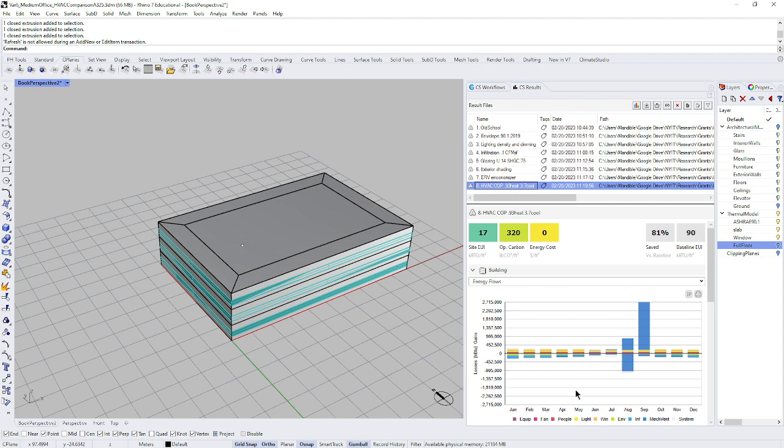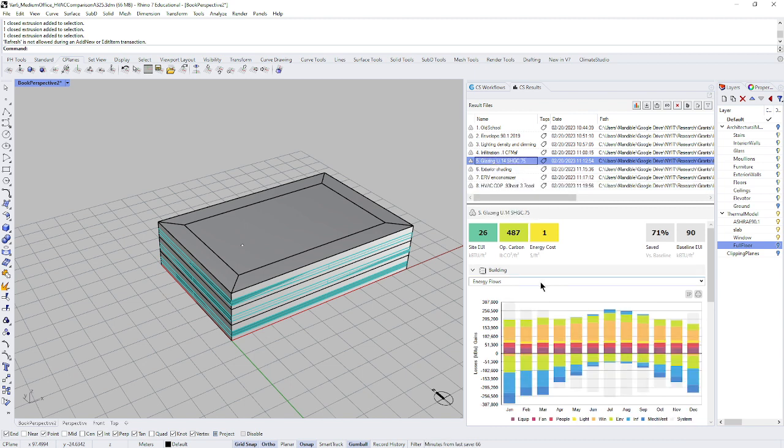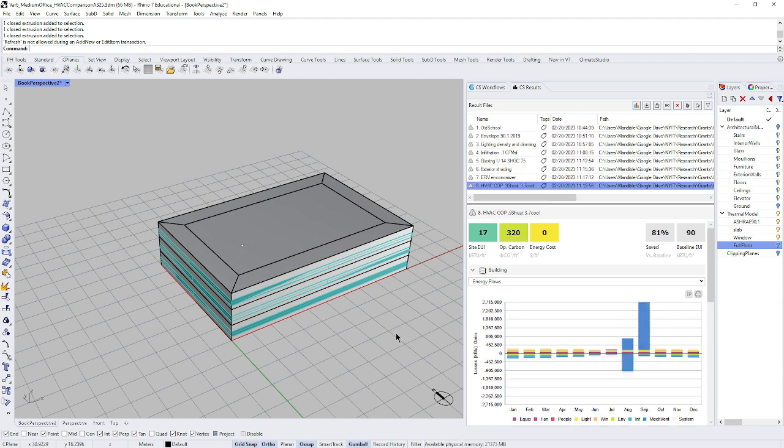Anyway, we're doing great. We got 81%. The reason why it seems so large, it's not that large. It's just because these are all so small. But if we go back, at some point we made that drastic change because we improved the other things enough so that the mechanical ventilation and infiltration became the most important. Only point here is that now I've got an optimized envelope, and we're going to use that a little later.